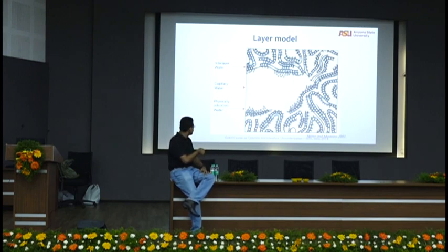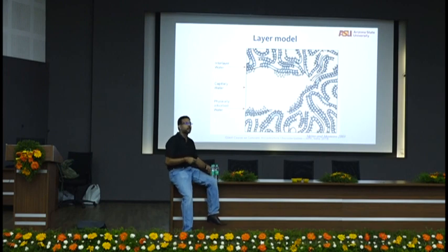And this capillary pore water, did that contribute to hydration? No, it's just staying there, right? It did not involve itself in any hydration products. But this water, the adsorbed water and the interlayer water, are part of the structure. They are part of CSH. They are the H of CSH. So if you want to know degree of hydration, you want to find out how much of the H is there in CSH. And if you look at books, when completely hydrated, how many grams of non-evaporable water can you get in 100 grams of cement?